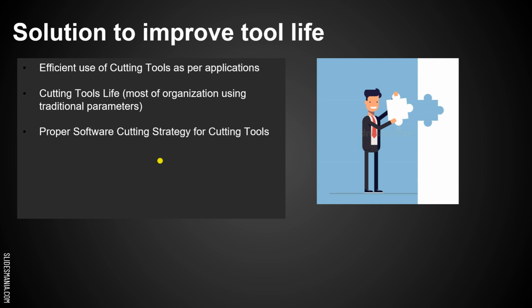Proper software cutting strategies for cutting tools, as I mentioned earlier. Cutting strategies like 3D finishing and 3D roughing. You have to select your cutting strategies and toolpath smartly. Knowledge of cutting tools and coolant selection as per cutting data.